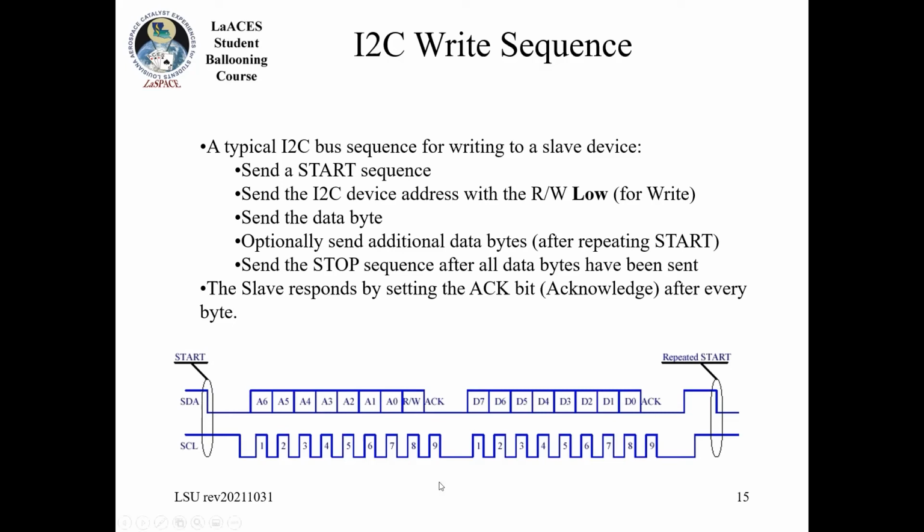So if I'm doing a write, I will send the address and then a write bit. I will get an acknowledgement back from the slave device that will tell me that it is actually receiving. So the master will get here, it'll wait, and then it'll basically look for the other device to ping the data line low on this clock.